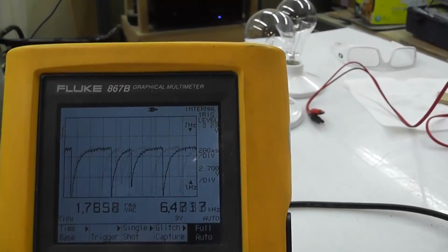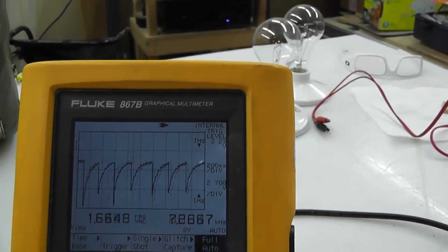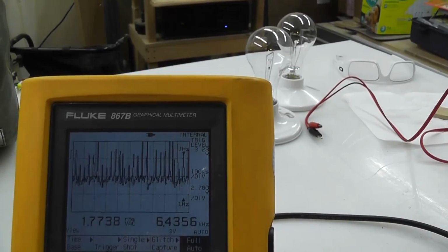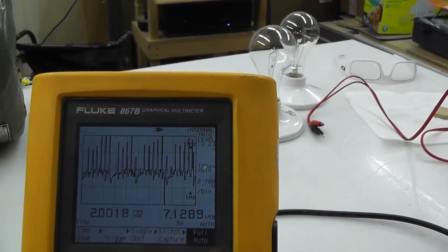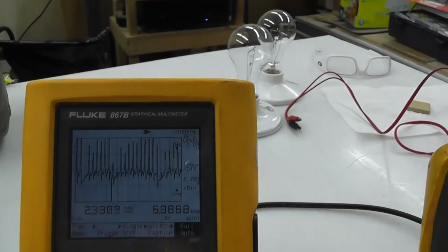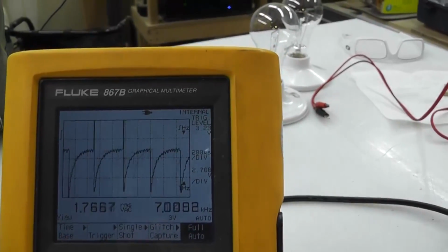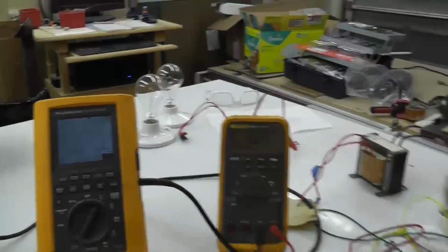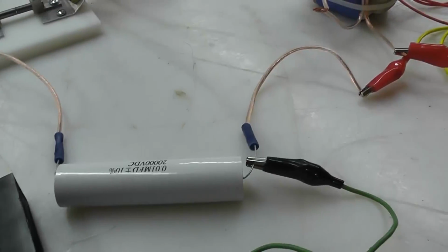That's pretty interesting. It's like it filters out the crap through the earth ground, and when you take the earth ground off, the reason the voltage looks so high is because of the noise that's actually on there, and it's harder to tell, since the meter doesn't know where the average is now. But I put the earth ground back on. Cleans it right up. I wish I had my oscilloscope. I would like to see this one actually. I could switch these meters around, I suppose. And the light bulb got a little bit dimmer due to what's going on over here. It fluctuates. It's more stable with a larger capacitor on here.